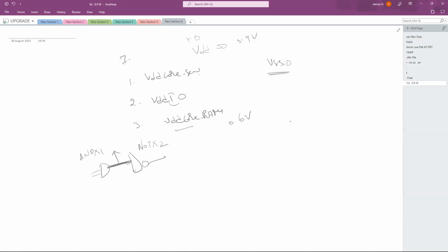Netlist format would be, Nagendra, are you there? Yes, sir. The netlist format, the output format, how do we recognize this is the netlist? .vg files. And what is .v? .v is Verilog code. So this is how you can differentiate: .vg is gate level Verilog code, meaning gate level netlist. Try to remember that.